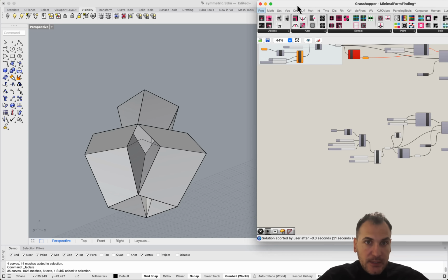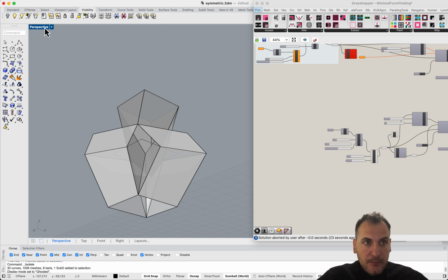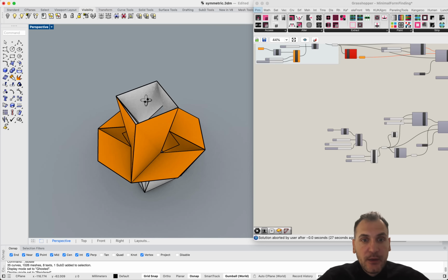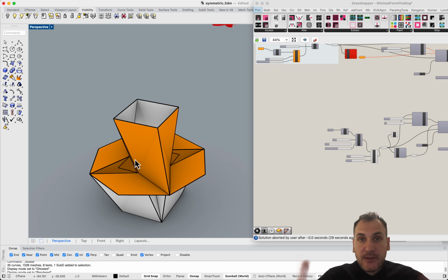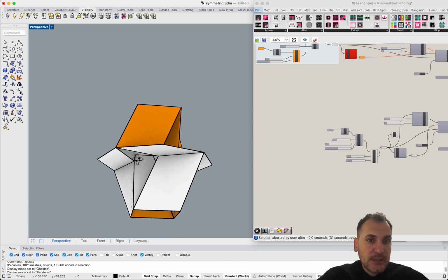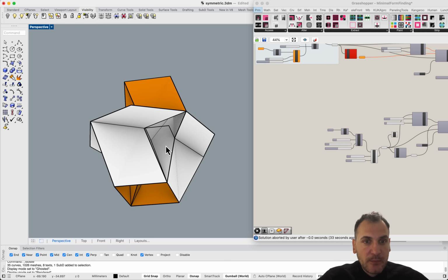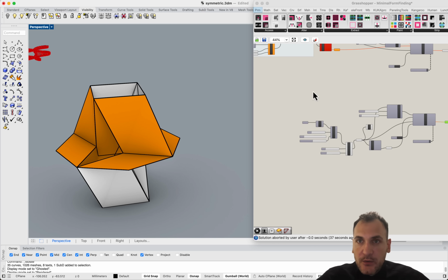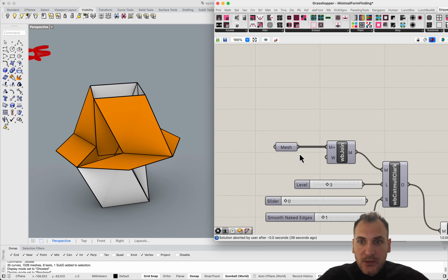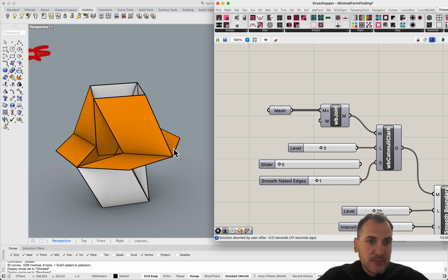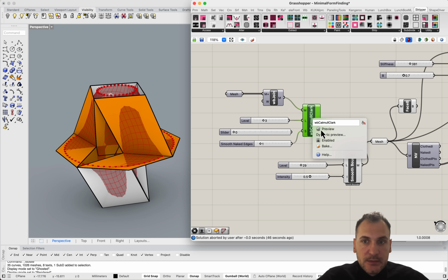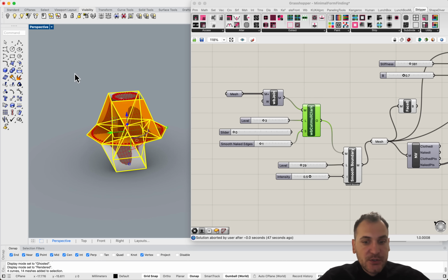And the nice thing about these is if you build, let's say the topology correctly, right? So we need to have faces that are facing inward and outward, right? So that's kind of these two colors, and you want to maintain continuity of surface construction. And once you build that, what this code can do is you can supply all the meshes, and this subdivision will first initially smooth it out, right?